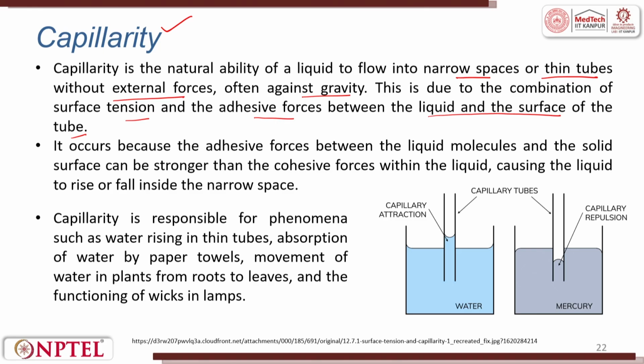So, capillarity as a property is the ability of a liquid to flow into narrow spaces or thin tubes. It occurs because adhesive forces between the liquid molecules and the solid surface can be stronger than cohesive forces within the liquid, causing the liquid to rise or fall inside the narrow space. For instance, here the forces are lesser, here the force becomes high, so it rises here. This is capillary attraction, right? Also, there could be capillary repulsion because mercury is having higher specific gravity. There is a capillarity repulsion here as well.